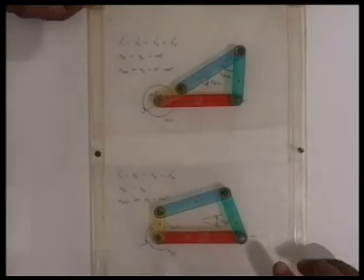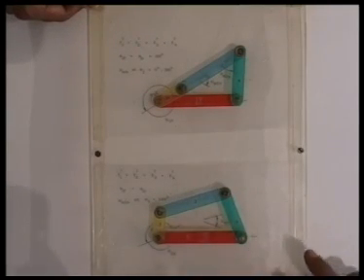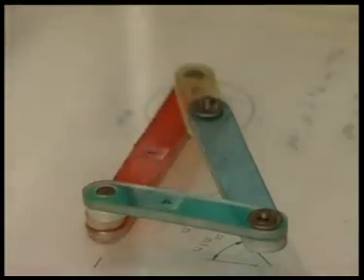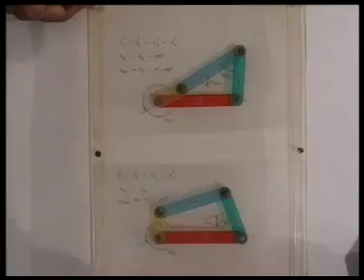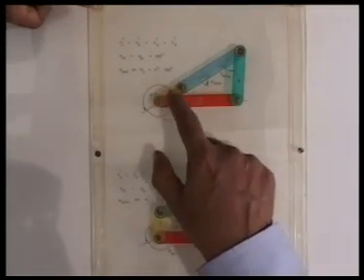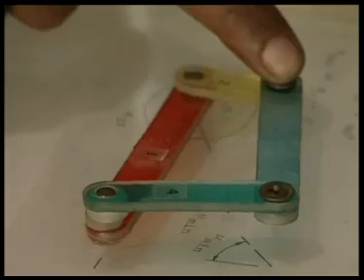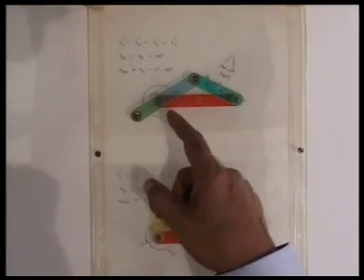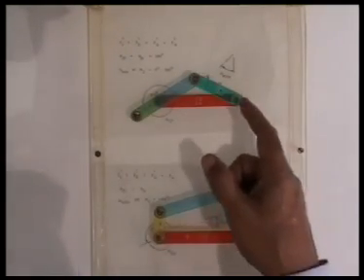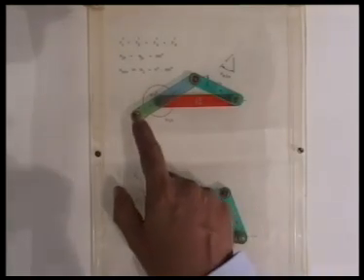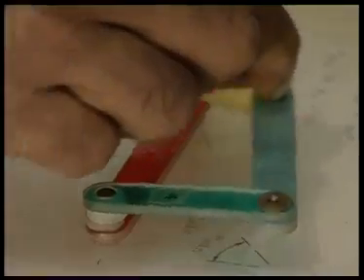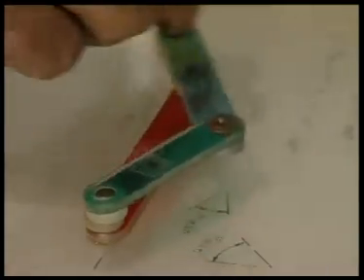Let us now look at the model of this Crankrocker linkage without quick return that we have just discussed. This is a Crankrocker linkage where L1 squared plus L2 squared is L3 squared plus L4 squared. This is one extreme position where the crank and the coupler have fallen in one line. This is one extreme position of the follower. Now, as it rotates through 180 degrees, again the crank and the coupler become collinear, giving rise to the other extreme position of the follower. As a result, in this 4R linkage, if the crank rotates at uniform speed, the forward and return motion of the follower takes equal time and there is no quick return.